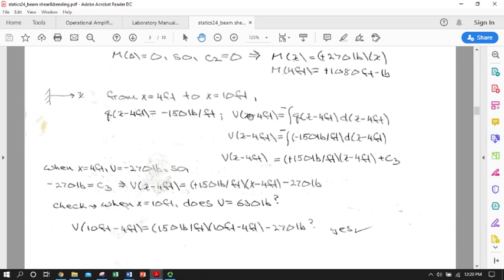Okay, so the shear force at any x minus 4 feet is going to be the integral of the distributed load times what we're integrating with respect to. So we've now substituted x minus 4 feet for x in everything to show that indexing over. We're doing this indexing because we're not using definite integrals. We're using indefinite and popping out an integration constant. We'll get away from this substituted offset when we go to definite integrals. It'll get a little bit easier.